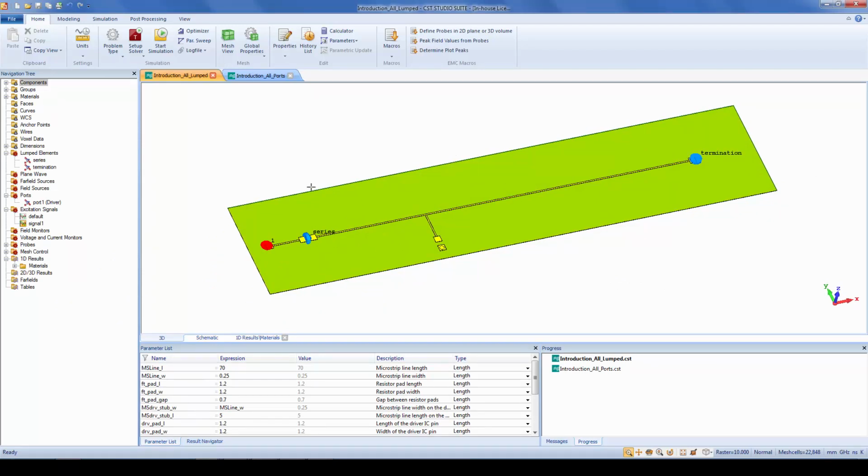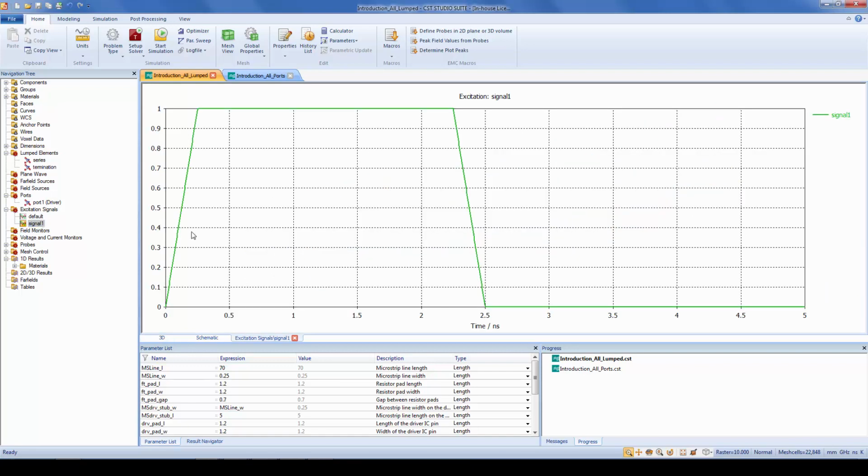And what I would like to do is drive this signal trace with a signal, which you can see here. It's basically a 200 megahertz signal, because we have 5 nanoseconds of time and we have a rise time of 250 picoseconds. So a pretty fast rise time, and this is the signal that I would like to drive the setup with. So I start the simulation straight away.